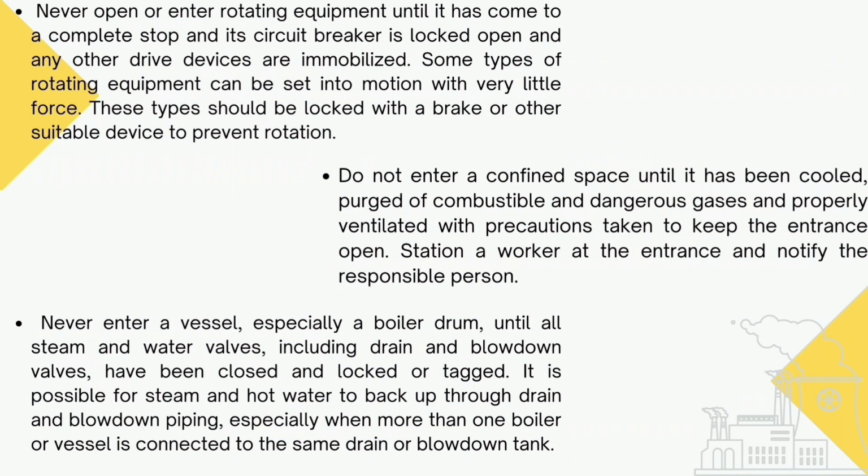Do not enter a confined space until it has cooled, been purged of combustible and dangerous gases, and been properly ventilated, with precautions taken to keep the entrance open. Station a worker at the entrance and notify the responsible person.